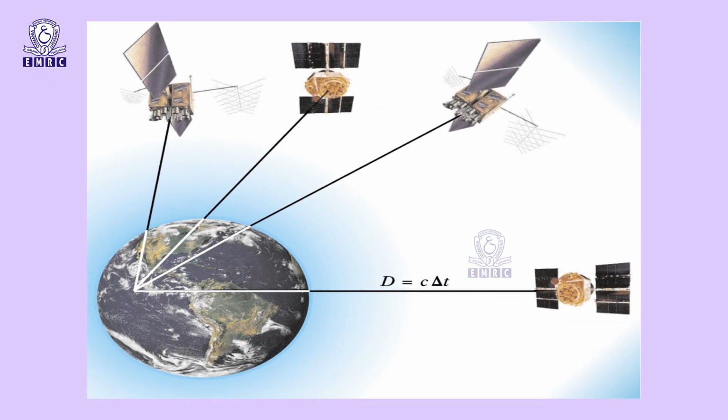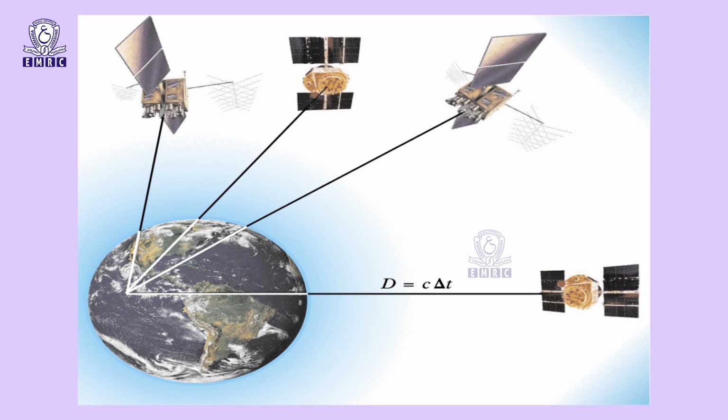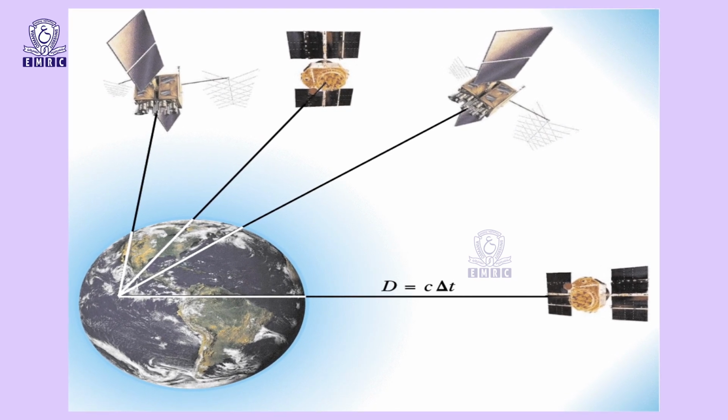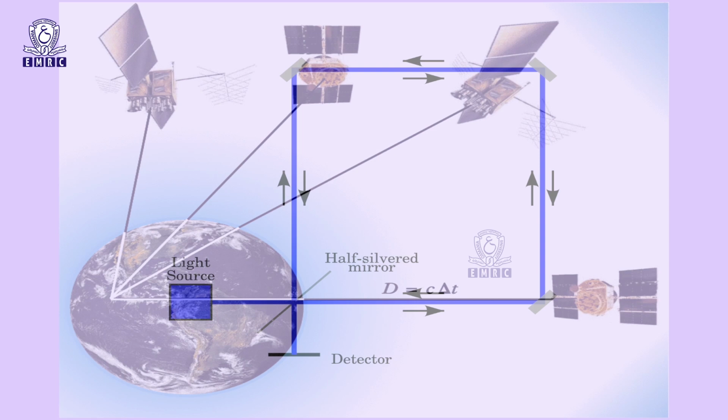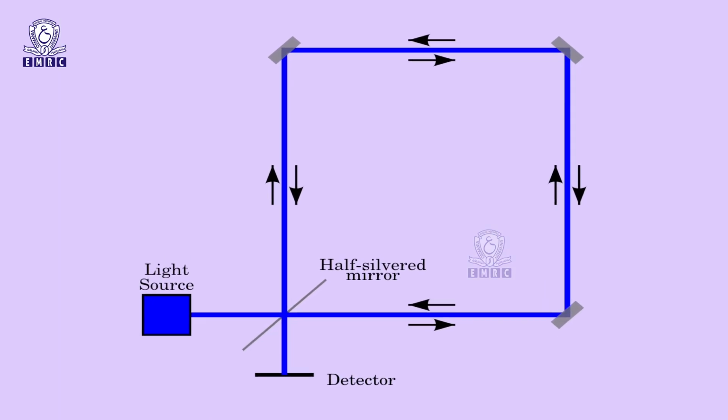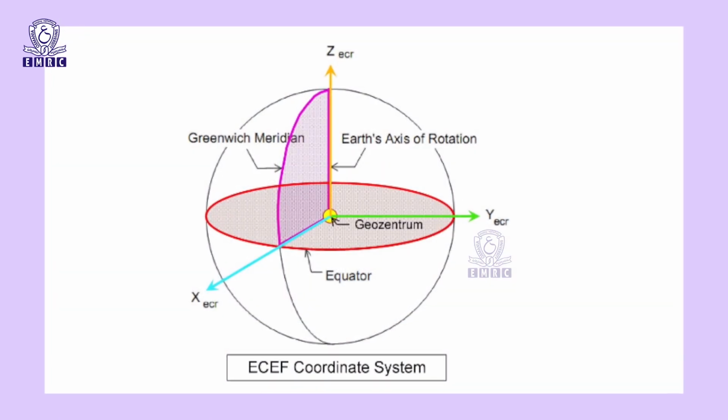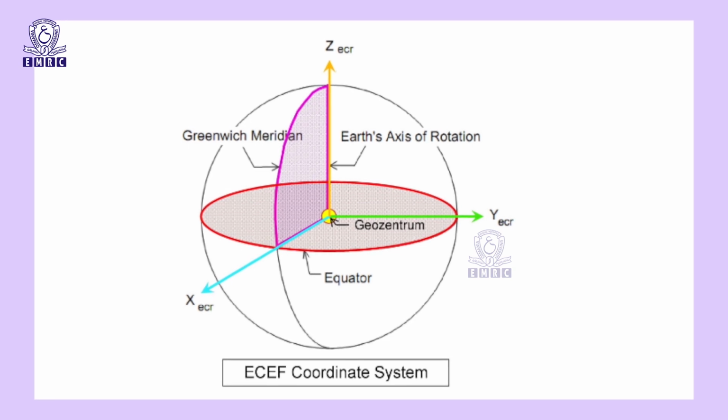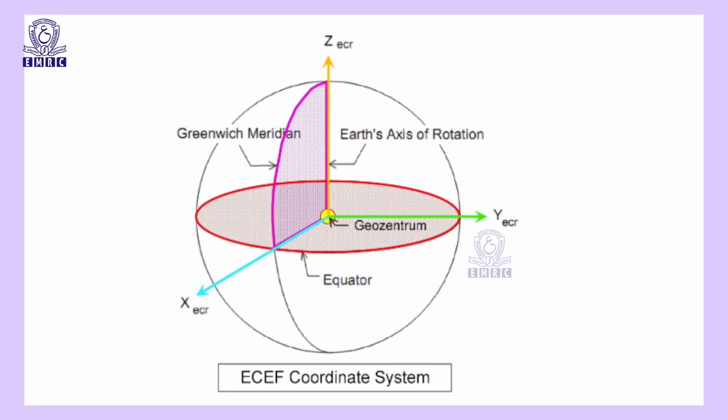Due to rotation of the earth during the time of signal transmission, a relativistic error is introduced known as the Sagnac effect. When computations for the satellite position are made in an ECEF coordinate system, during the propagation time of the SV signal transmission, a clock on the surface of the earth will experience a finite rotation with respect to an ECI coordinate system.